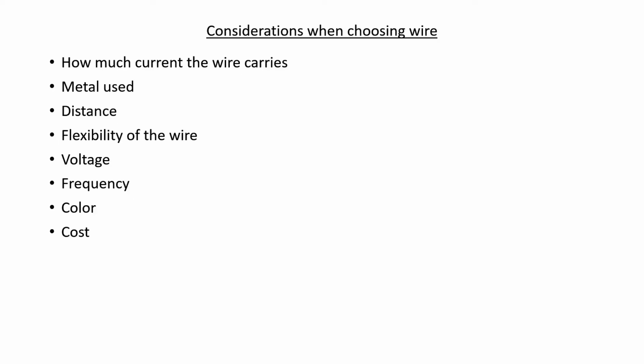There is one practical consideration, and I'd want to point this out. Aluminum is more difficult to solder to. Copper wiring is really easy to make solder joints to, but aluminum tends to be very difficult. So it's just something to keep in mind if you, for example, want to use aluminum wiring to make a drone. I mentioned earlier in this video that one also needs to consider the frequency of a signal passing through the wire.